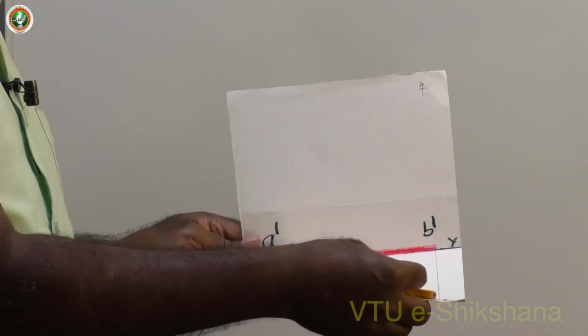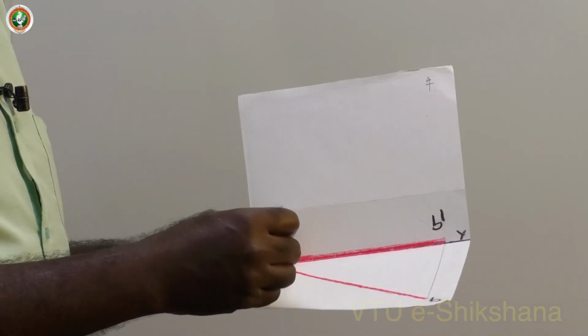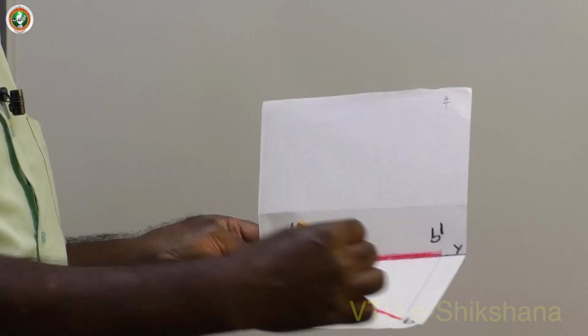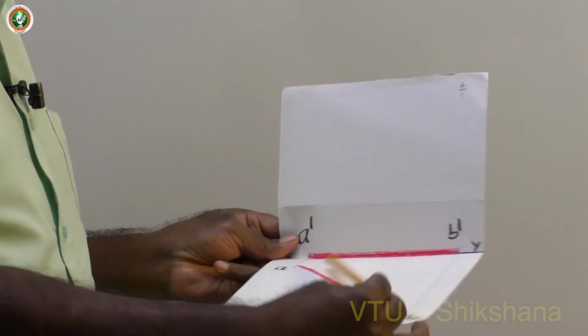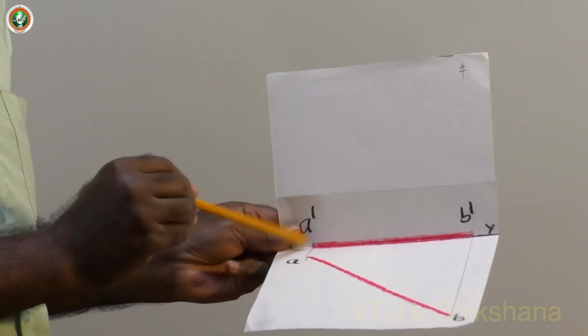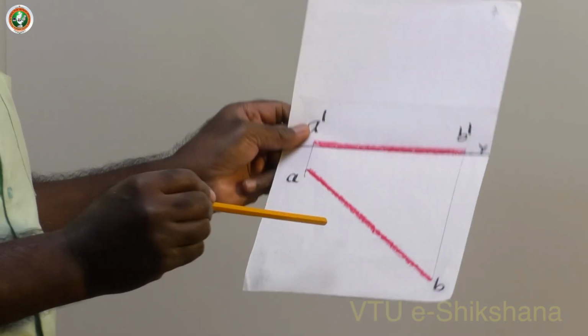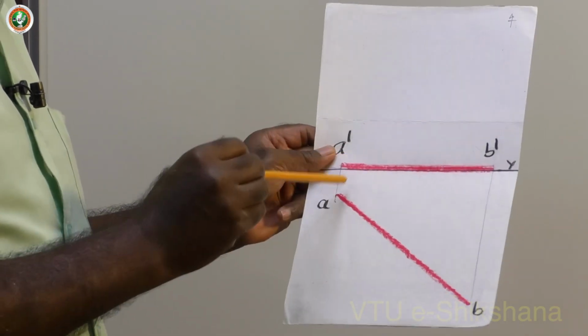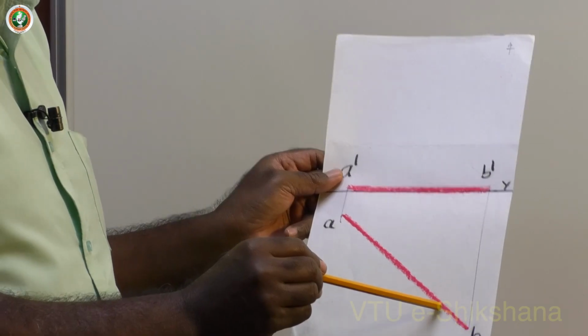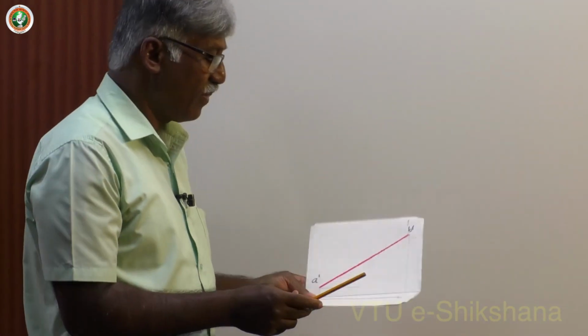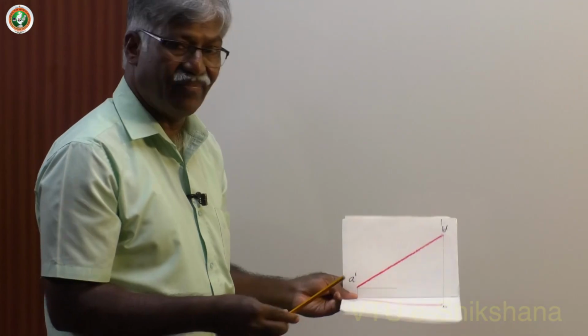Now the front view is touching XY line because it is on HP and inclined at some degree, and one end is 20 mm in front of VP, say. Now I can say the line is on HP and inclined at some degree to VP. Now take two more important simple problems and discuss with simple models.